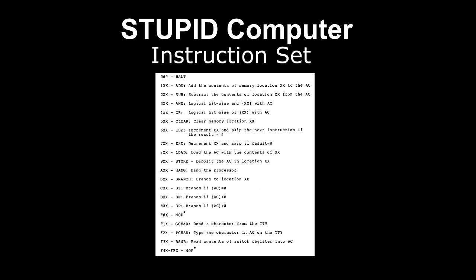Okay, so let's take a look at the instruction set. Again, 12 bits, and it's a single word per instruction. There's no fancy, multi-word instructions like you see in a lot of processors today. Oh, and of course, being limited to 256 bytes of microcode, and including in the microcode a power-on self-test, it's a rather limited instruction set. The way the instructions are encoded, the high 4 bits, or the high nibble of the word, is the opcode, and then the remaining 8 bits can be an address in memory, or they can be further decoded, which you'll see in the F instructions down at the bottom.